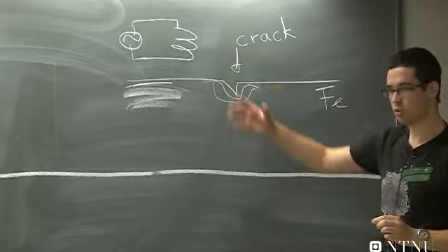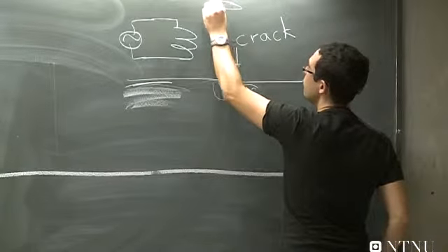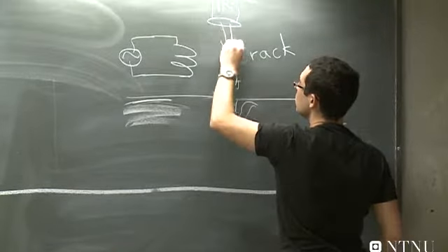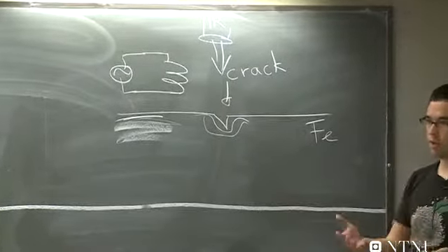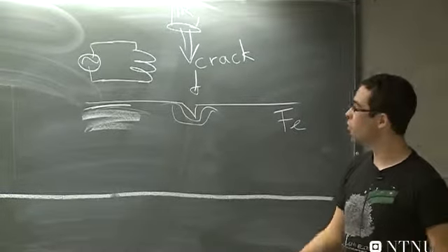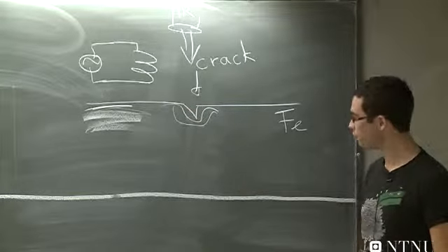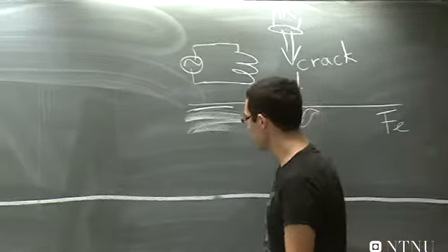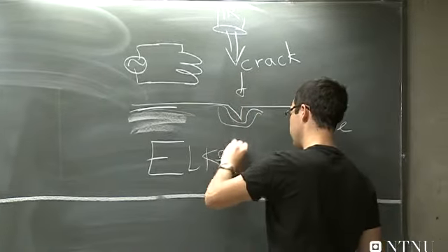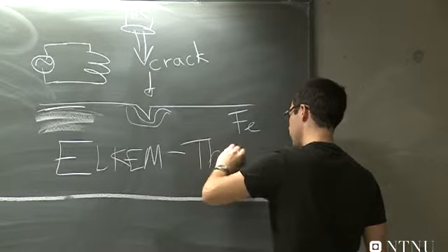So in addition to this coil stuff, which sort of generates surface heating, I put an IR camera pointed towards the crack, or the place I think there might be a crack. And if I see some local heating from the infrared camera, well, then there's a crack at that spot. This was developed by Elkem. And it's known as something like the thermomatic.